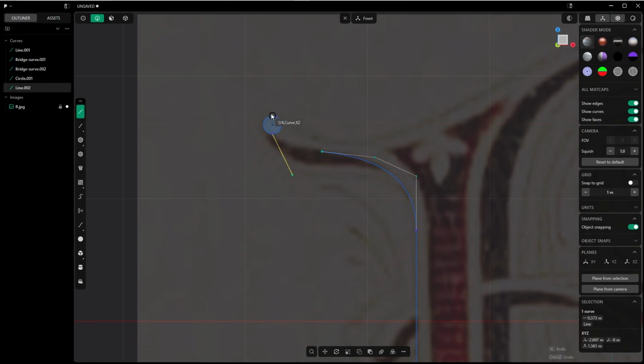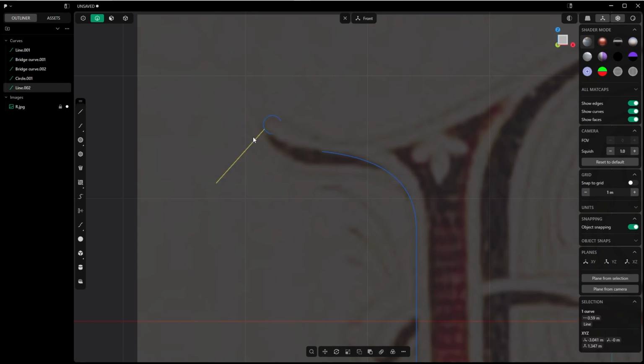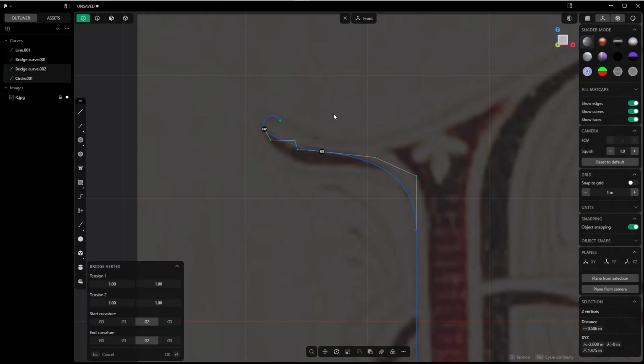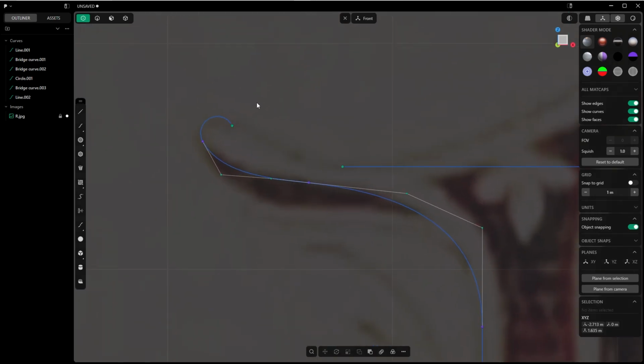Create two lines. And I will use these ones for trimming this part. And if I'm not pleased, I can again trim. And now in control point mode, select these two, press L. That looks okay to me. I press OK. And here I again create a horizontal line, a perfect horizontal line, again for lofting these two. But here I'm not pleased with this endpoint, so I will again trim it. Yeah, trim it here at this snapping point.